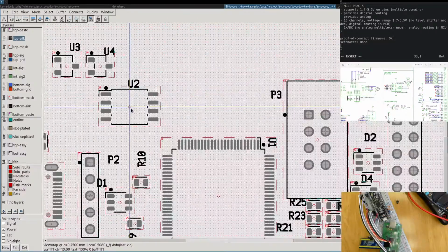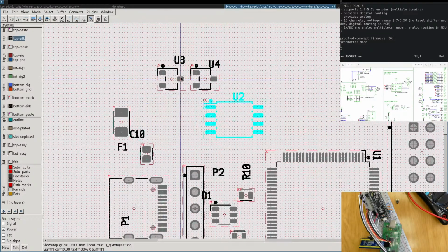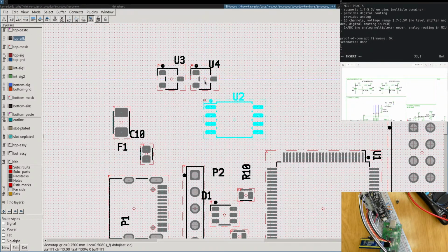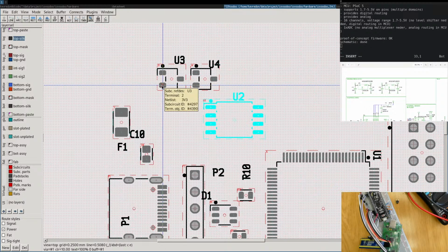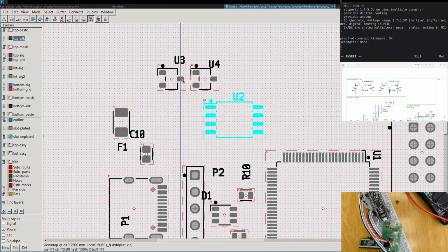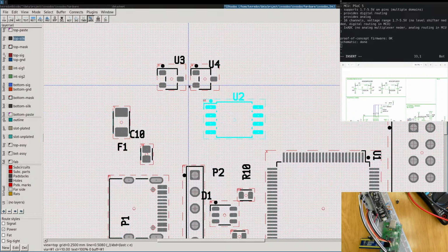So here these are the voltage regulators. Yeah, they're fine here. We have to put the capacitors next to the voltage regulators. So input should be left, then output should be right. This is output, ground. This is in. Okay. So the 5-volt input comes from the fuse.